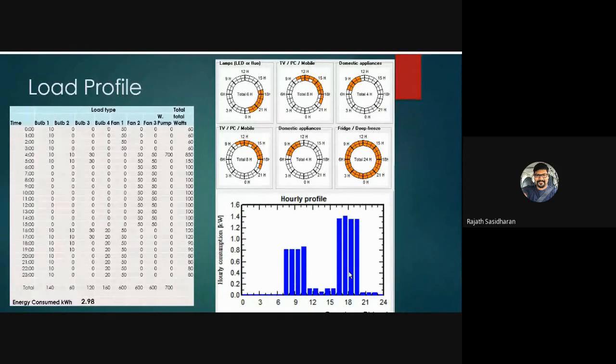So say you are getting 60 amps out of the MPPT charge controller, and it is coming to the same bus terminal where everything is parallel, and say 30 amps is taken by the battery inverter, and the rest 30 amps is injected into the battery. So that's how the daytime working is done.